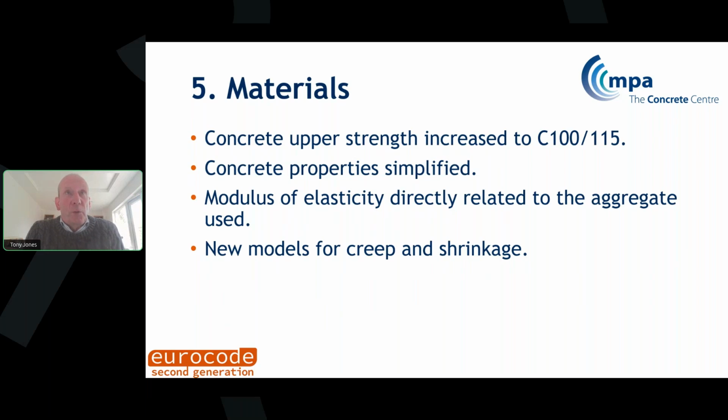There are also new models for creep and shrinkage. It's important to realise that with the shrinkage model, there is no size effect on the shrinkage at time infinity. So it actually is important now to consider the design life of your element when you're considering the appropriate design shrinkage to use.